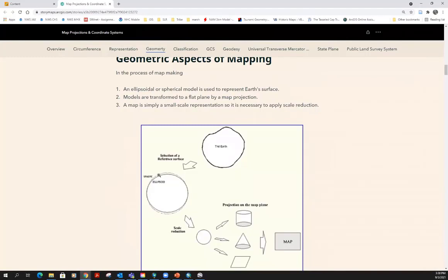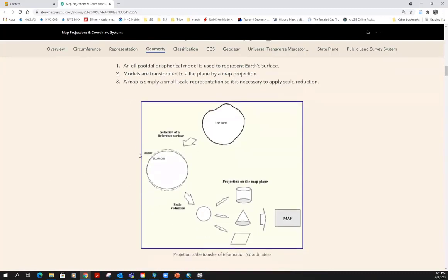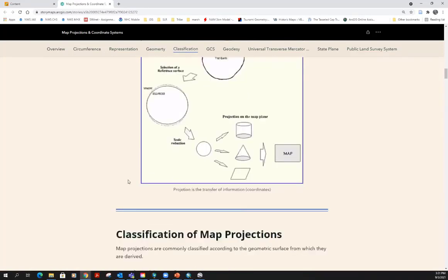The next is a little section about the geometry: the Earth is not a perfect sphere. It is squashed at the poles, with centrifugal force acting on it from its rotation. If you took a basketball and pushed down on the top and bottom, and had about a 3% bulging at the equator, that's approximately what you would have with the Earth. So we have to project locations on a sphere onto one of these 3 types of flat surfaces. They're not flat when shown here as a cylinder or a plane, but you can unfold those to create a flat 2-dimensional map.